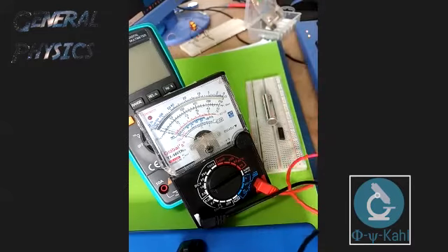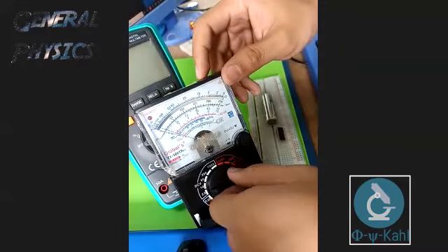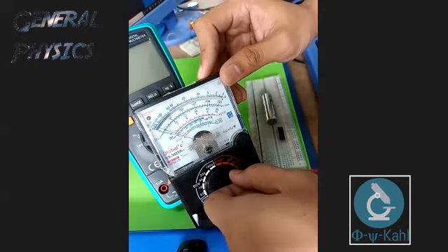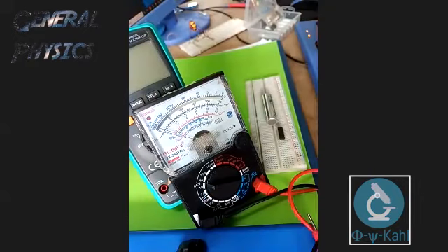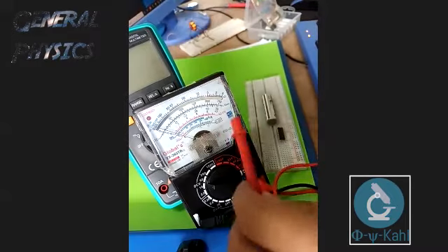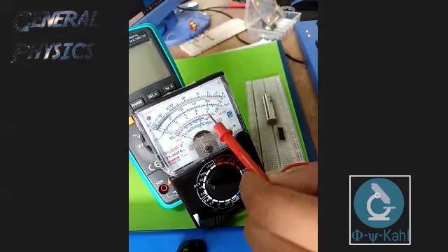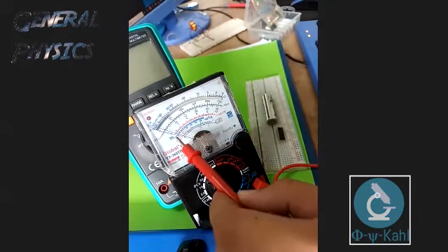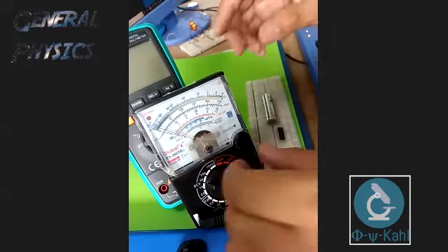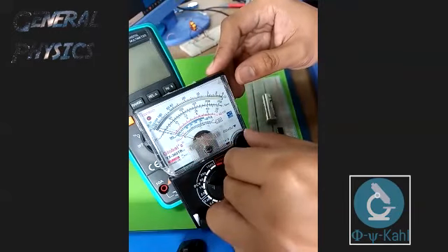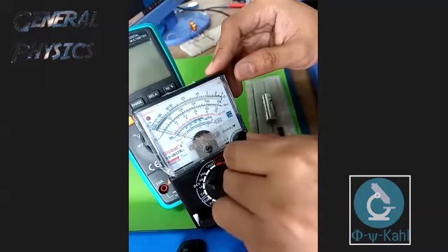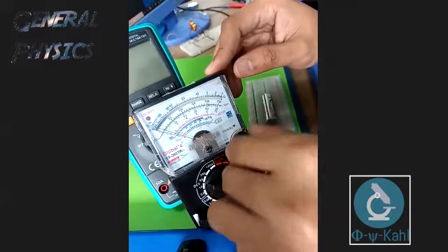To make our readings accurate, I will set my analog pointer to 10. So I want to show 10, 20, 30. Where is that? I have here the maximum value of 10. So you have 8, 6, 4, 2, 0. Our multimeter right now is not pointing to 0, so I need to adjust it.